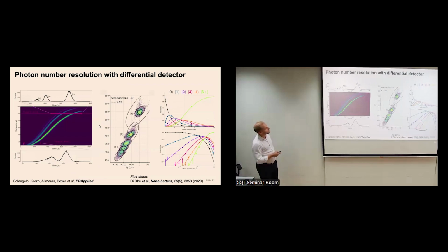So these are blobs of post-processing data, looking at the timing resolution or rising edge slopes. You can really see a blob for 1 photon, 2 photon. It starts to smear off at higher photon numbers. So you really want to use this detector to distinguish between 1, 2, or maybe 2 or more photons.